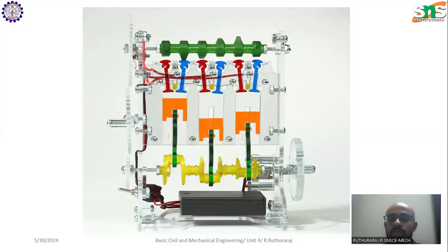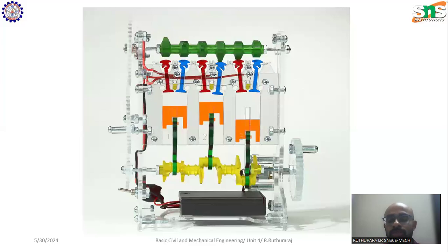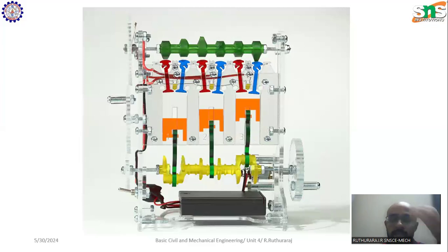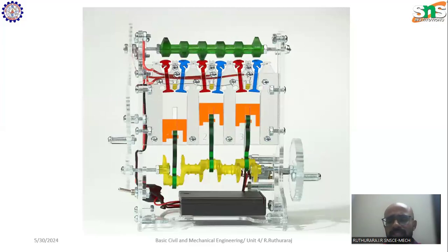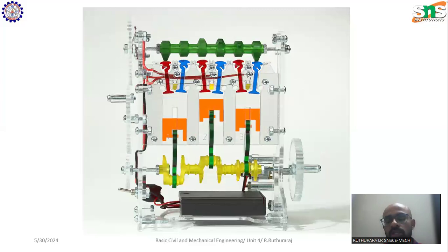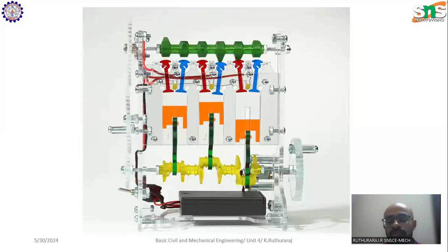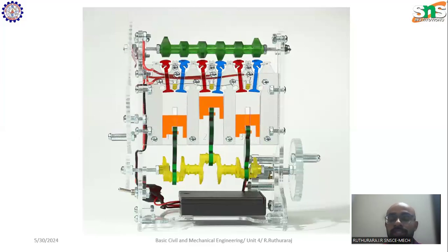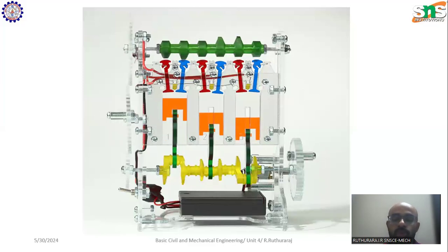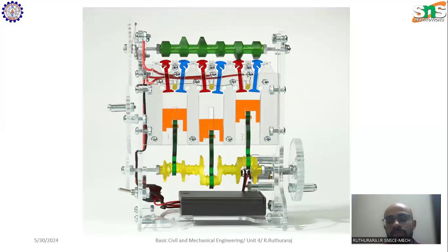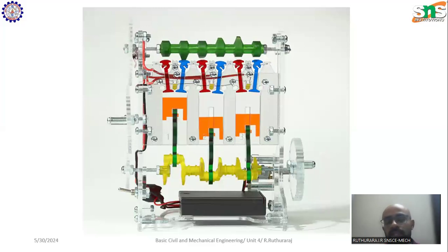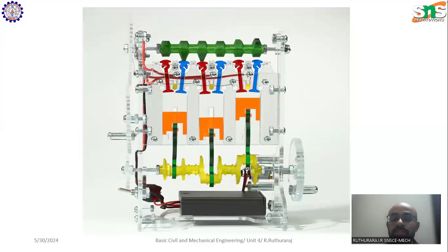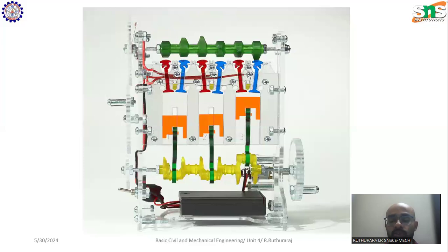It is happening with the help of a flywheel. So the flywheel is nothing but a large wheel with huge mass. If you have seen the conventional diesel engines which are used to pump water from the well, in olden days, there would be a diesel engine which would start by rotating a big wheel. So that wheel is actually called a flywheel. The purpose of the flywheel is that it stores the energy. It is an energy storage device.